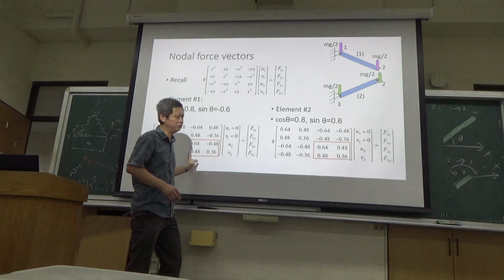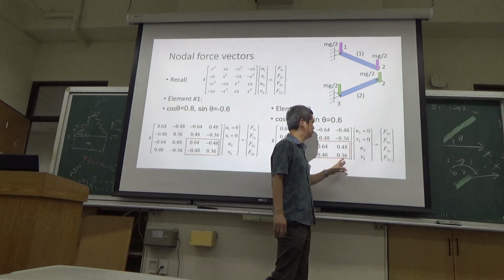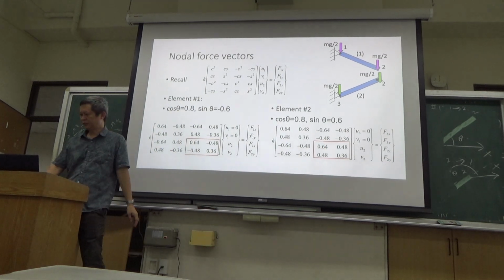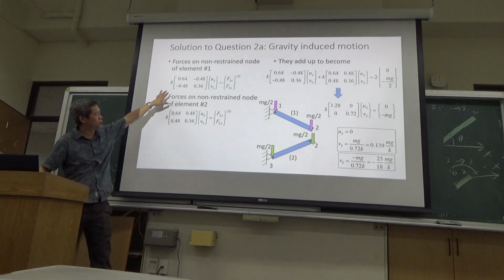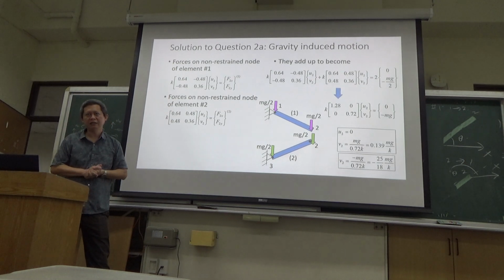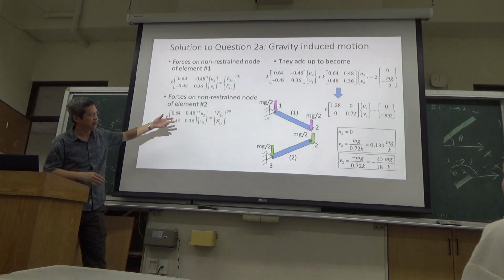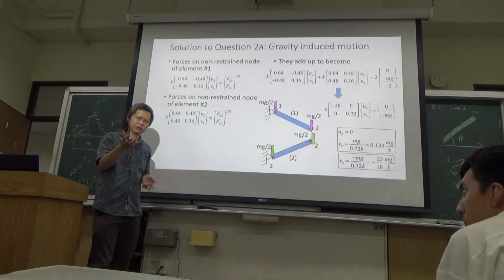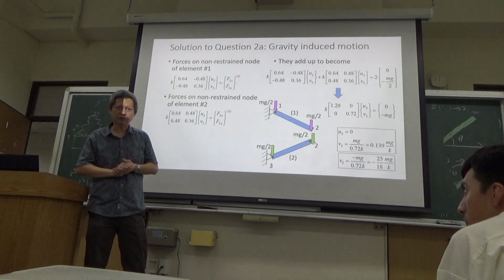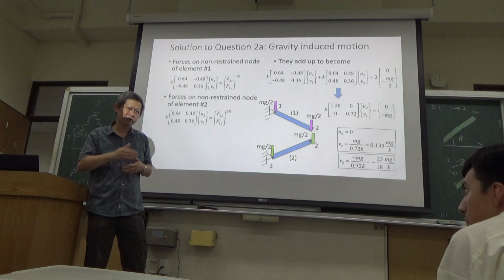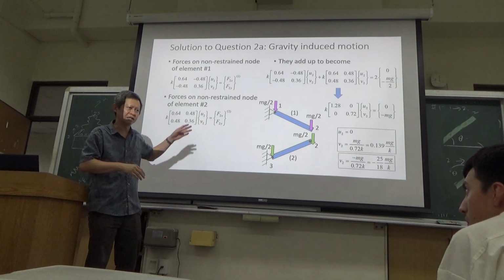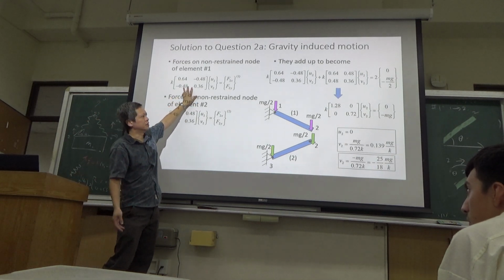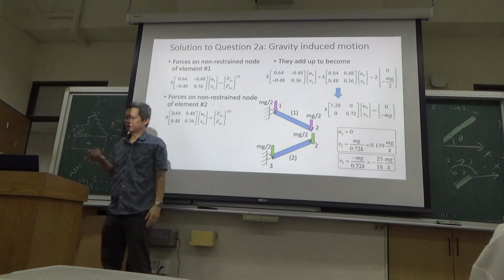You only handle the non-zero displacement. You only handle the stiffness components associated with the non-zero displacement. Then these two you sum. Please go back and try it out. Exercise with the right practice. I know that you could refer to the answer from your textbook, but the answer in the textbook doesn't help you because they are following a procedure which has no physical meaning. You better learn from your mechanics, Hooke's law, then handle them properly. Then you get the right answer.